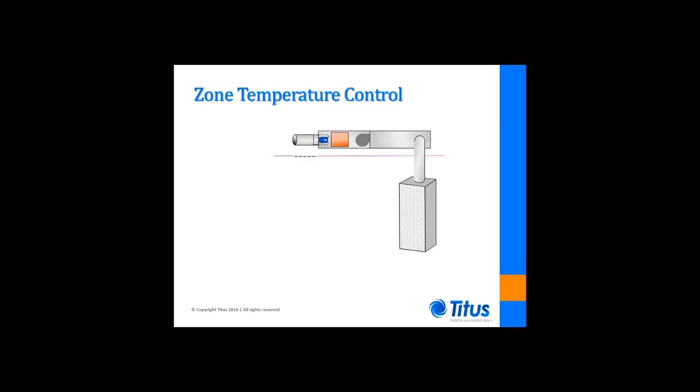Proper zone temperature control is critical to achieving this enhanced level of contaminant removal. In order to satisfy space cooling demand, the supply air volume flow rate and/or temperature has to be varied. One commonly used method involves the use of series fan terminal units.